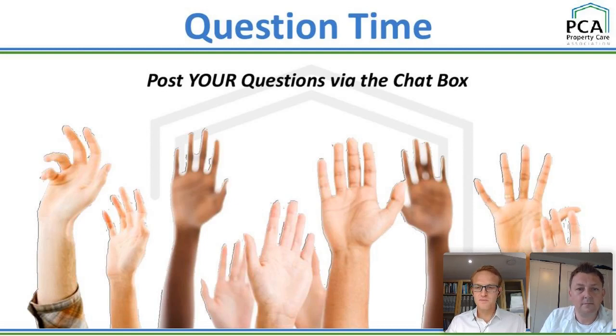I think you would expect that if it was going to fail, it would probably do so in the first 10 years or 20 years, that sort of thing. So I still think there's merit in that. My bigger issue would be with your waterproofing admixtures. They're very limited in their value, and you've got to prove that it's the admixture that went wrong. And often that just comes down to commercials.